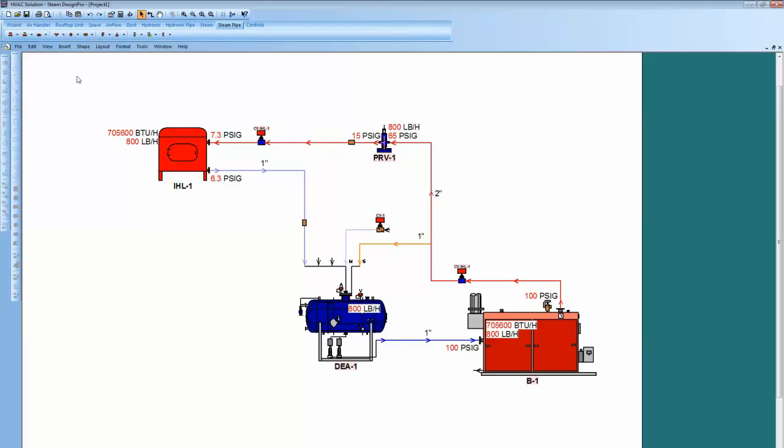Okay. ASHRAE defines BIM as being able to optimize systems. And with the software, that's just what you can do. You can go in and look at changing what-if scenarios. What if I change the pipe size and make it larger or smaller? How does that affect my velocities and my loads?